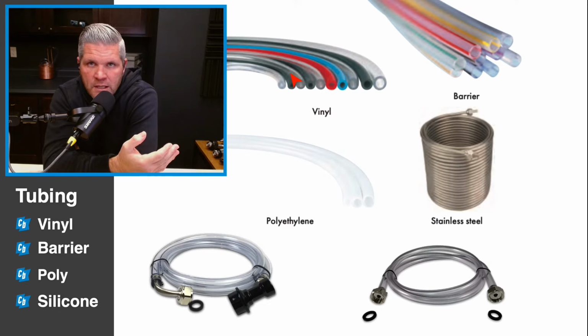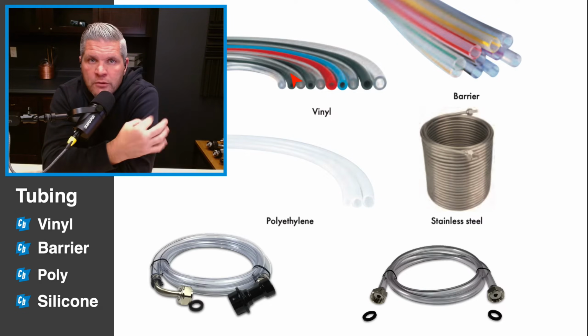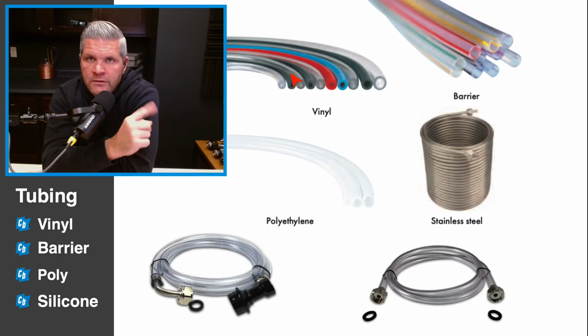So if you're using a jockey box, or you're in a direct draw situation where your kegs are attached inside of a kegerator, if you've got mold growth, you can see it, right? The only time that you would use colored tubing out in the field would be to prevent light strike on the beer, and you'll see that in a jockey box setup. But again, while it's good for preventing light strike, because you're using it over and over again, if somebody doesn't clean it, you're going to know right away.